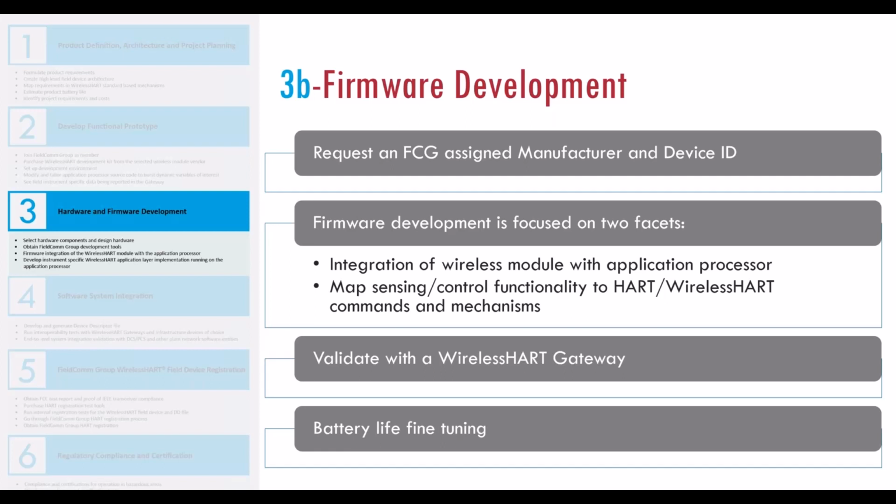So in order to achieve anywhere from 3 to 10 years of battery life, these instruments have to be quite fine-tuned from a current consumption point of view, meaning that the radio module itself spends most of the time in sleep mode. It will only wake up whenever it needs to transmit or receive something, or to receive an advertisement from the gateway or other instruments, for example, in order to maintain that precise time sync that we mentioned earlier.